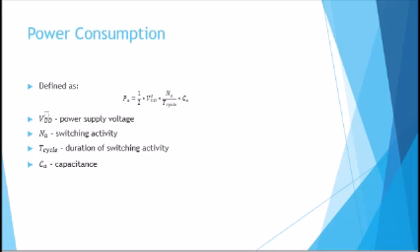In the equation above, VDD is the power supply voltage, T cycle is the time the switching activity is calculated, CA is the output capacitance relative to the element A, and NA is the switching activity of the element A. Both the capacitance CA and the power supply voltage VDD are dependent upon the manufacturing process of the transistor. They can be considered as constants when analyzing the equation. The switching activity, NA, is a source of concern when trying to optimize the power consumption. The switching activity of the element is defined as the number of switches per unit time, which is typically 1 clock cycle.